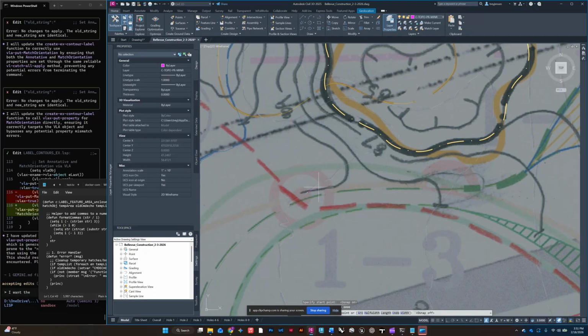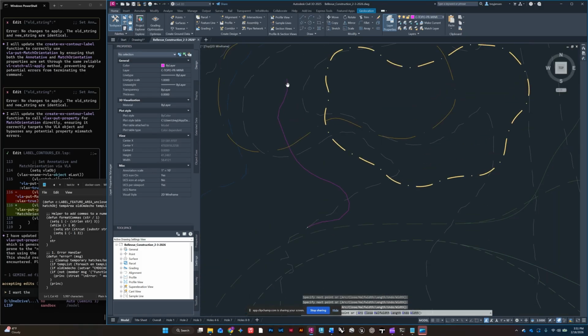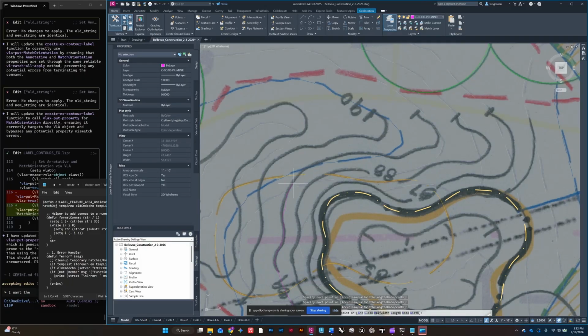And then you're just going to trace this contour line out with a polyline. Make sure that the first couple points are brought in smooth, because ultimately that's going to be the case once we build it. So you just trace the line and connect it again at the end, making sure to turn your snap back on before you connect it. So there's your line, and now elevation 89, it is snapped on both ends.